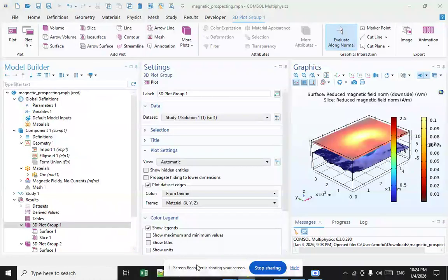The free program MicroDEM converts the USGS elevation data into an ASCII file containing the elevation matrix, which you can import into COMSOL Multiphysics as an interpolation function feature. From the interpolation function, you can then create a geometry by using a parametric surface feature.